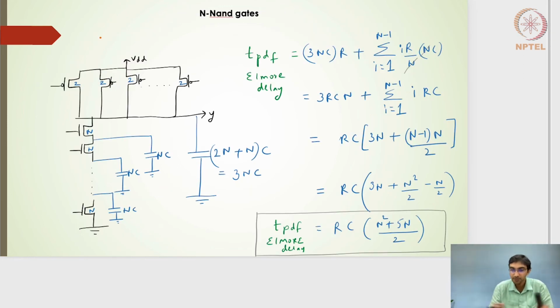And just to complete the overall logical efforts and the parasitic delay, basically the linear delay model, what I've done here in the next 2 slides, including this one, is try to showcase the Elmore delay model based delay estimation, and compare it with that of the linear delay model with respect to the number of inputs. So I've taken a simple example of an n input NAND gate. So for an n input NAND gate, I will have n such PMOS transistors and n such NMOS transistors.